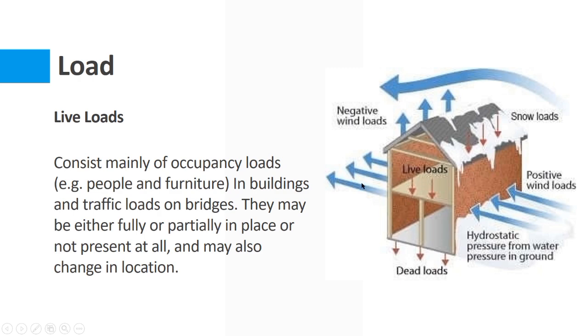Now the load of the 50 students is a live load, and when we are designing the building, we have to take a load of 50 students, but it is not possible that at any time all 50 students will be present. It is possible, but most of the time maybe 38, 40, or 45 students are present, and they will be present in school time and on the weekdays.